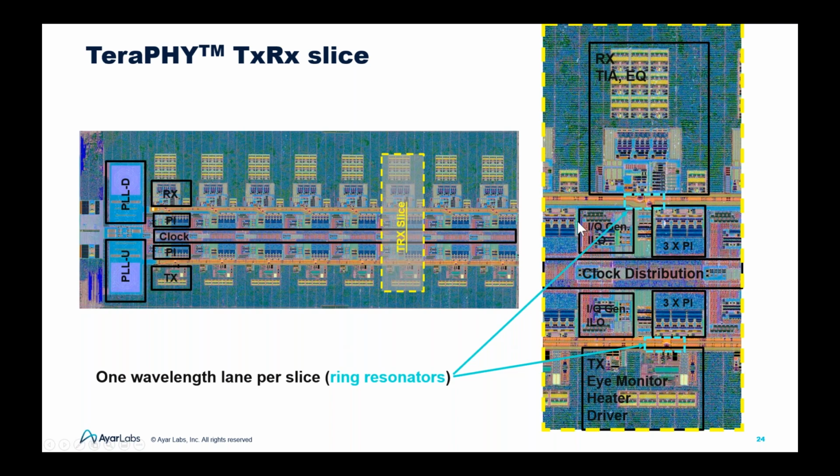But one thing I would like to point out here: if you see these 2 small dots and 1 single dot here, these are the ring resonators. One of them acts as a modulator, 2 of them are for the receiver, and one of them acts as a dummy. Then you see how optics is still small compared to the electronics if we move to the ring. But if you use the standard Mach-Zehnder, we are talking about a much larger area than this. And these two red colors here are our optical guide.